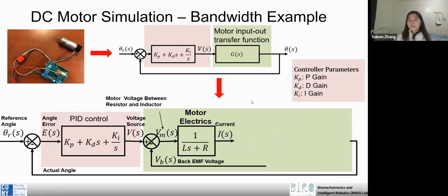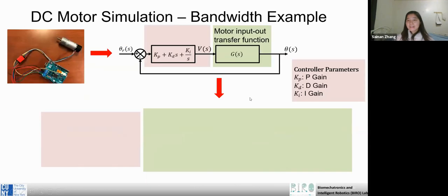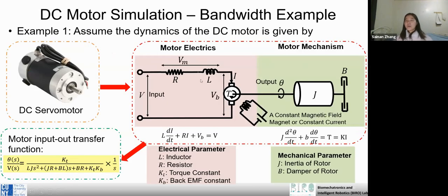And we can think about this DC motor. We will find there is no gear ratio. That means the gear ratio equals 0. And for this kind of actuator, this is the ideal actuator. But why don't we use the direct drive motor actuator? This is because the motor can only generate a small torque.